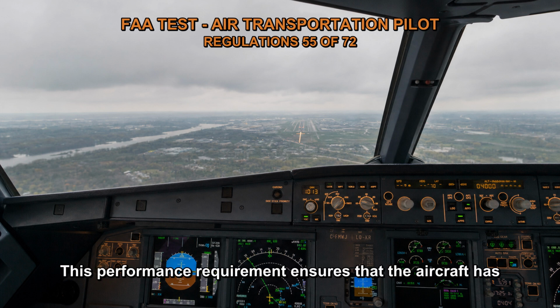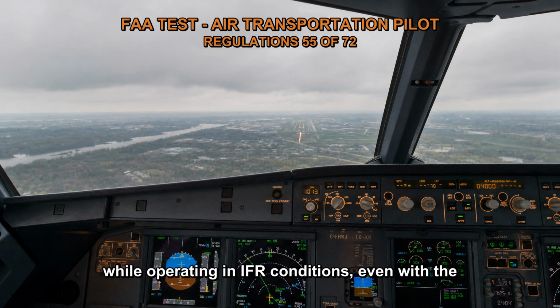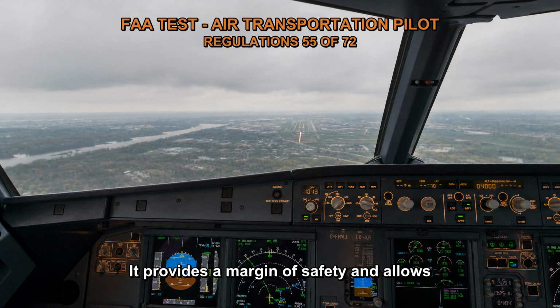This performance requirement ensures that the aircraft has adequate climb capability to maintain a safe altitude while operating in IFR conditions, even with the loss of one engine. It provides a margin of safety and allows the aircraft to clear obstacles and maintain the required minimum altitude along the route.